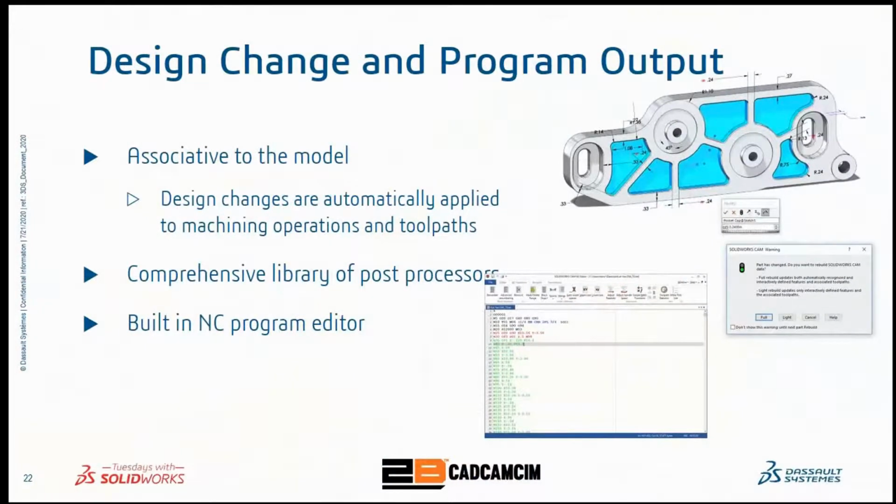So now we have seen how SolidWorks provides us with an associative environment between CAD and CAM. So simply, after we make any change to our CAD project, you will find the CAM environment updates the toolpath and the code according to these changes, which helps us reduce time, and we don't need to repeat the whole procedure again from the beginning if we add any kind of modification.